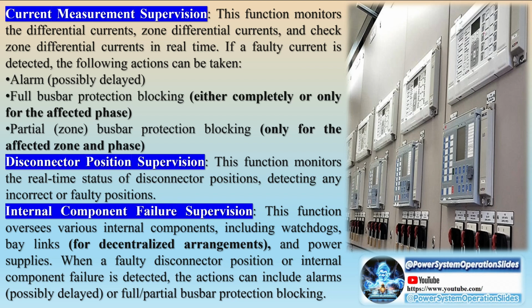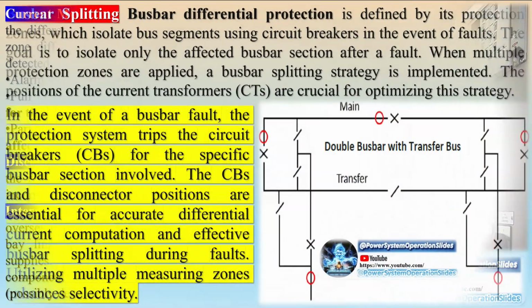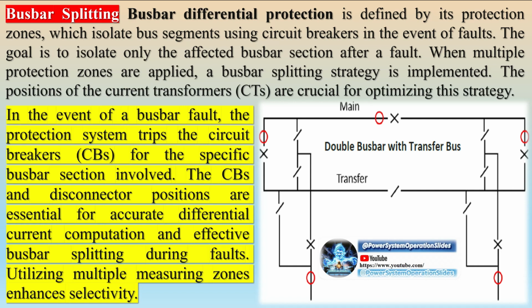Currently, low-impedance differential relays are more commonly used, although high-impedance relays are still in use by some operators. Each type has its own advantages and disadvantages. Low-impedance relays offer the benefits mentioned earlier, while high-impedance relays are easier to extend, require less space, and are less expensive. However, low-impedance relay hardware can be shared with breaker failure protection, reducing costs. Users must evaluate and choose the best solution based on their specific application and installation needs.